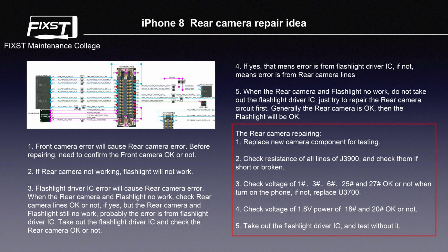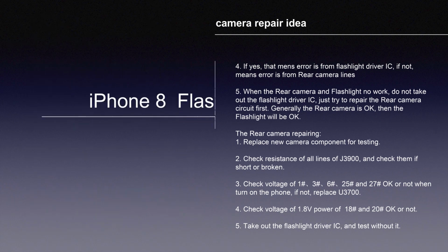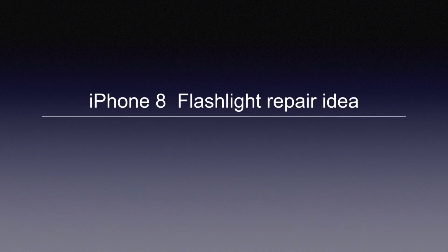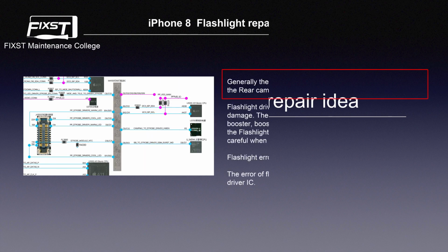Number 4. Check the 1.8 voltage power of pin 18 and pin 20. Number 5. Take out the flashlight driver IC and test without it. Next, iPhone 8 flashlight repair idea.